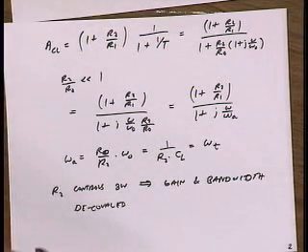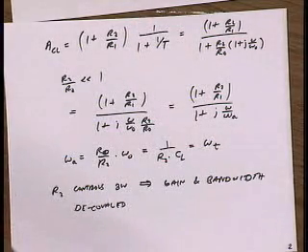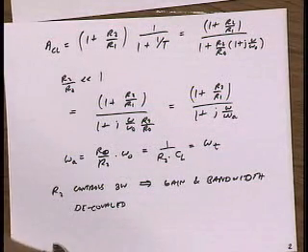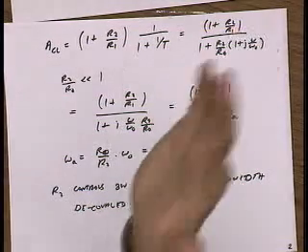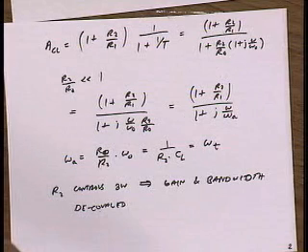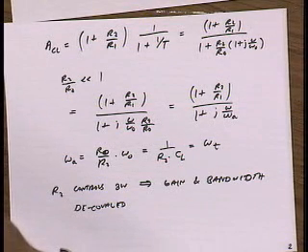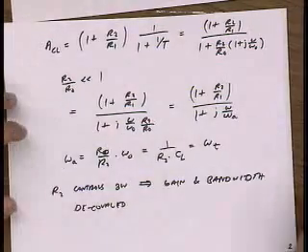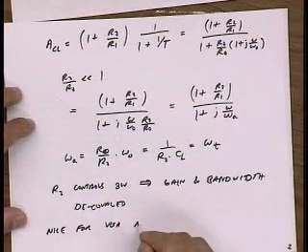If you're using a voltage feedback amplifier, you know that the more gain you want, the less bandwidth you're going to get. Okay? So it's just nice to know that no matter what gain setting I choose, I'm going to get the same bandwidth. Any particular kind of amplifier where that would be important? Anybody? Yeah. Variable gain. Yeah, very good. So this is very nice for VGA applications.